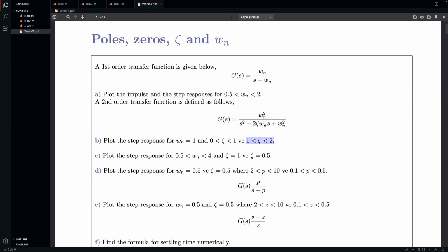If it's between 1 and 2, we have too much friction, too high of a damping ratio. Therefore, the behavior is not quite what we want. It behaves like a first order system anyways, and we don't really have formulas for design. So we would rather stick with this one here. If we want 0 overshoot, then we just choose zeta equals 1. But other than that, most of the time we will be lying between 0 and 1 for zeta.